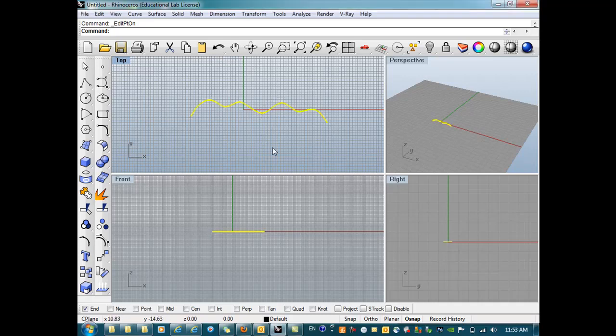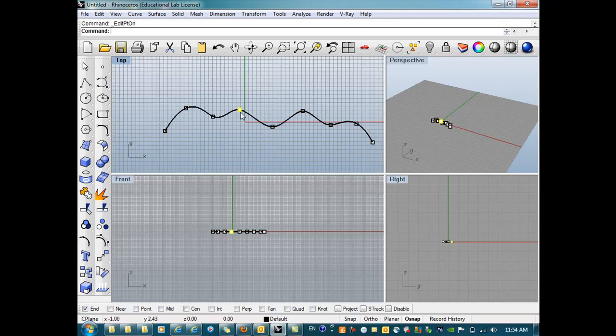So once you finish creating the curve, is it just a line, or a curve? You know, you did it using the control points, but now they're all gone. We need to bring the control points out. So we need to go to this toolbar, which is Edit Control Points. Click on it. So we can select any of them and just drag.